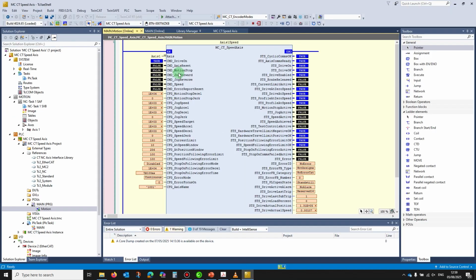So next thing, we've got axis reset, so that if you ever cause a PLC open type error, like you put in something like a speed that's bigger than 50,000 units, your upper limit, you would need to use axis reset in order to reset that. But equally, if the drive's got a trip, then you can see that drive OK is false, then you can use axis reset to reset the drive as well. So no matter what type of thing it is that you're trying to reset, this is like a universal reset, it does everything.